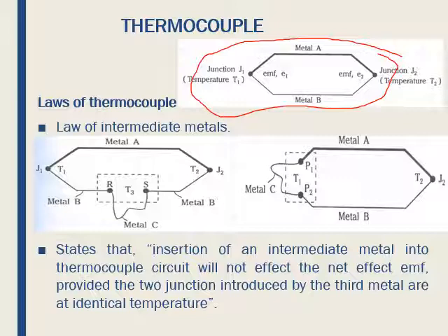Advantages of thermocouples are that they are inexpensive, there is no resistance lead wire problem, they have the fastest response, are simple and rugged, and have high temperature of operation. Limitations are tip or end temperature sensing, least sensitive, non-linear, low voltage, least stable and repeatable.